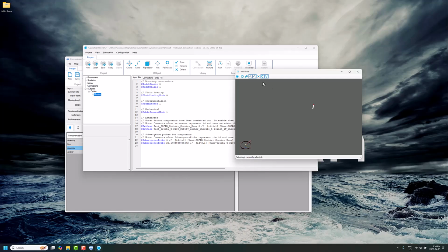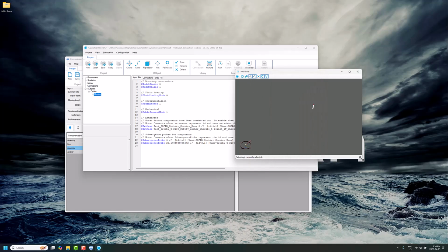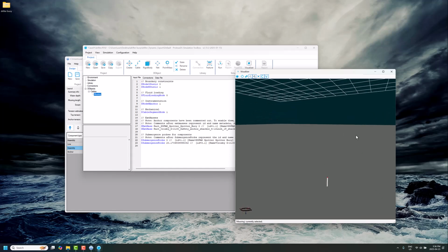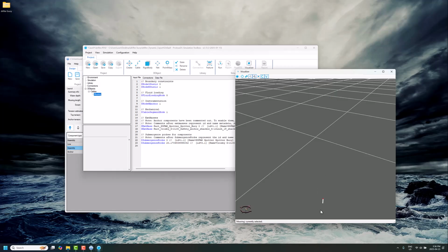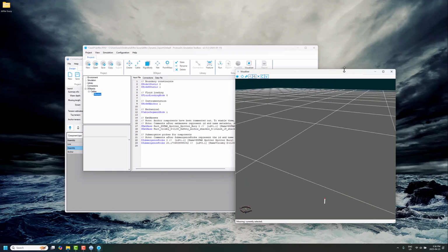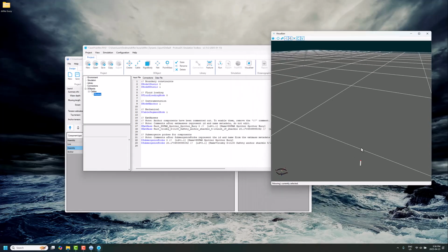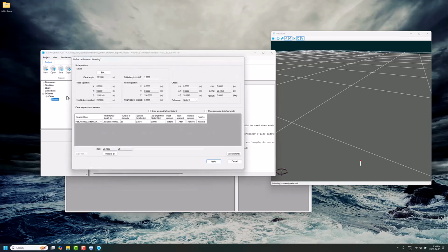Normally what Oceanographic Designer is trying to do is say, oh, well, the bottom is obviously going to be where the anchor is. And if you look at this, you'll see, oops, well, then that short 20 meters length of wire is way down at the bottom of the sea. So rather than running a simulation and letting this slowly float to the surface, we'll just quickly change the state. So click on State, and we'll go Edit.